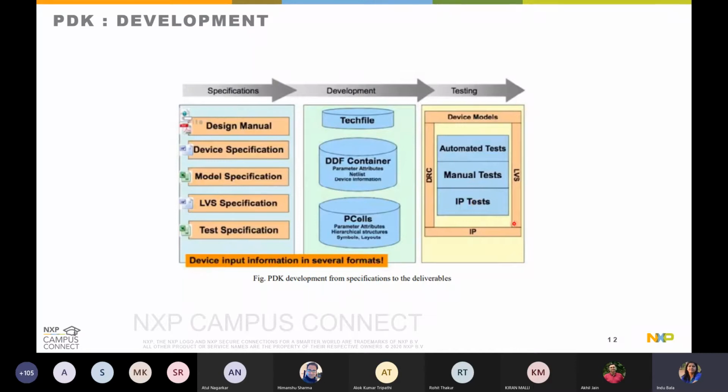So first we do the unit-level testing for all the components, which here is on DRC, LVS, device models, or IPs. Then the integration testing is done, especially for all the devices which are placed. You can create a common test case using all the devices, and make sure that the run flows fine and you don't see any issues during DRC, LVS, extraction or simulation.